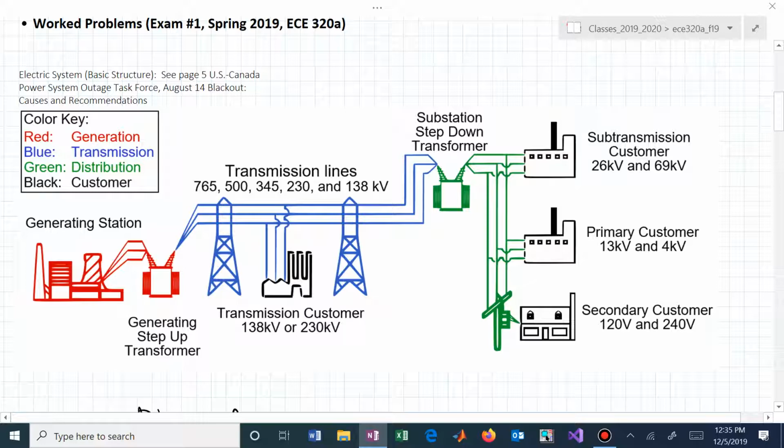Here's the picture that you can maybe keep in mind. We have generation and then we have consumption. And in between that is sort of where we deal with. We may not worry so much about the transformer stepping up the voltage and the transformer stepping down the voltage, but we are interested in what are we generating power-wise, complex power, and what are we receiving. As a primary customer, I know we don't like to be referred to as secondary, but we are secondary customers generally, unless we're at a larger manufacturing facility or another industrial plant. Then you might be a primary customer, and your voltage levels coming in are much higher at that location than they are if you are a secondary customer.